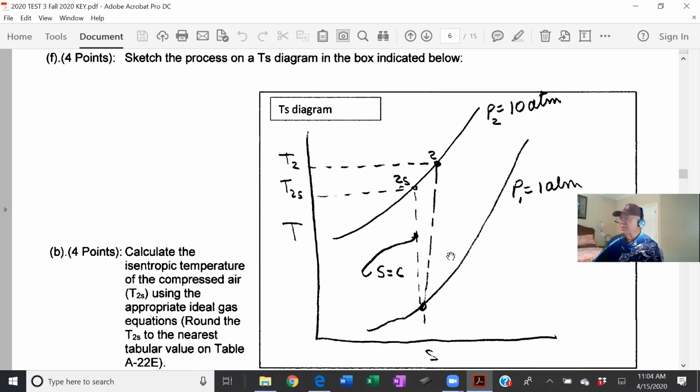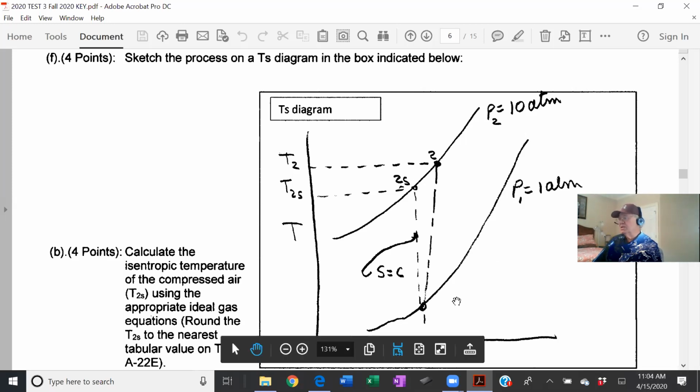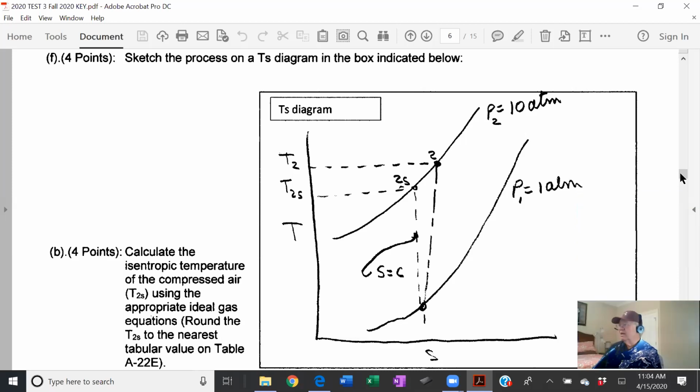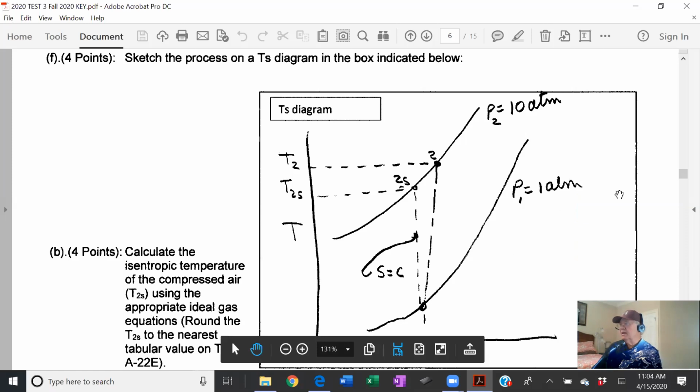But when you take the ratio and get the isentropic turbine efficiency, it doesn't matter whether it's H1 minus H2S over H1 minus H2, or like the book, H2S minus H1 over H2 minus H1. Believe me, you'll come out with the exact same answer, and it won't foul you up. It's a good question, Kelly, and I wish I'd explained that in class.